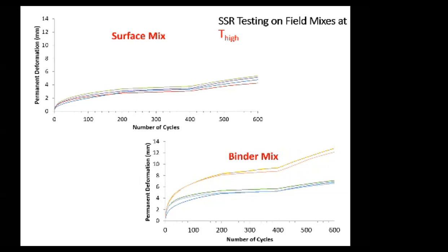Again, each specimen came from a mix from a different location. These mixes we're testing are from the same airport, but some are from taxiway C, some are from runway W, in the west runway. So they're from different places, but the same mix design though. Okay. So maybe there was a problem in mix fabrication or in mix laydown and compaction.